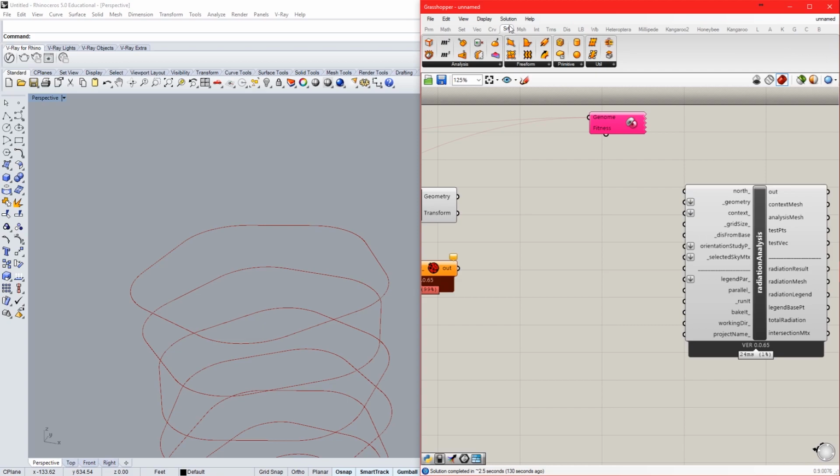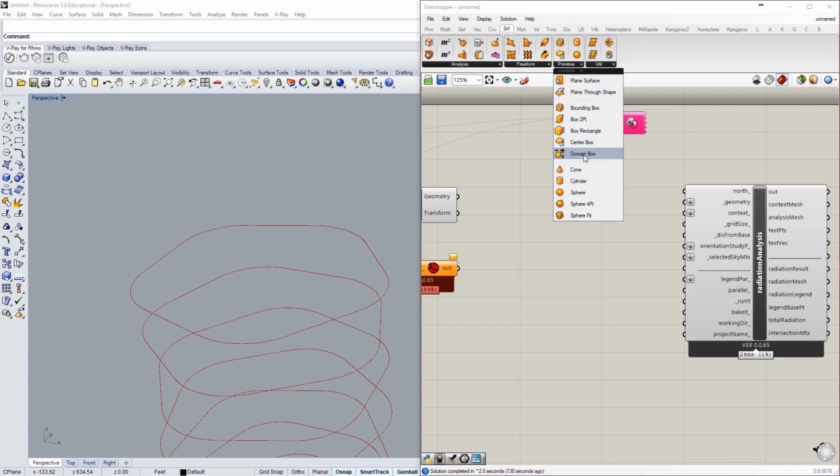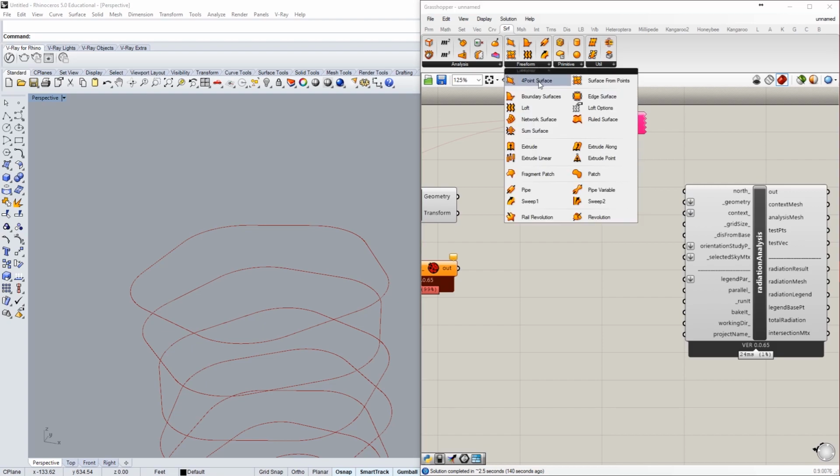So we go to surface, right? Freeform or primitive. I can look at primitive and I see that this is mostly 3D shapes. Not really what I'm looking for, unless trying to extrude the floors, but that's not necessary in this case. And go to freeform. After searching a bit for freeform, I can find boundary surface, create a planar surface from a collection of boundary edge curves, right?